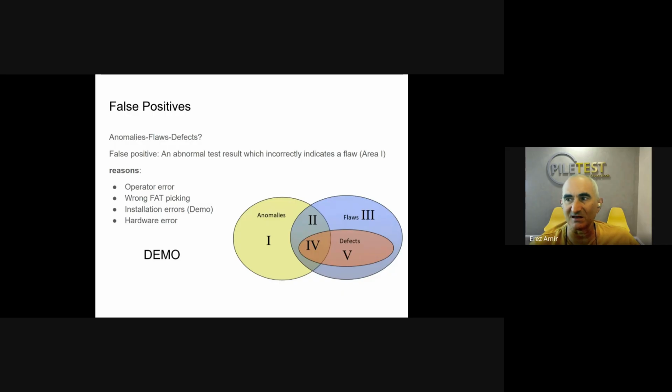That means, for example, the tubes are not parallel. The tubes were welded with excessive sleeves that created some kind of a gap. Debonding, typically in PVC tubes, that's a problem. Or even sometimes we forgot to put water in the tubes. And of course, there's also a reason for hardware error. If you have an old system which already has loose contacts and worn out parts, that's a problem.